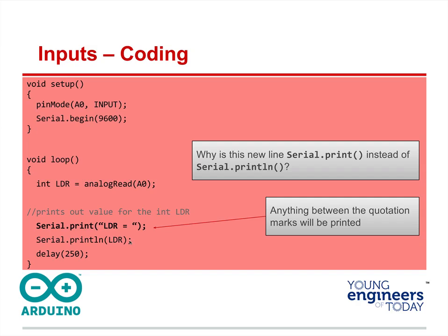And what that's going to do is now print, and I want you to try it here, take a moment and pause it, but it will print, and you should get LDR equals space the value of LDR. Because in this case, it's not skipping a line, so this will print right after it on the same horizontal line. But because of that line in, it's going to go on to the next one. All right? Make sure you type it and try it out.